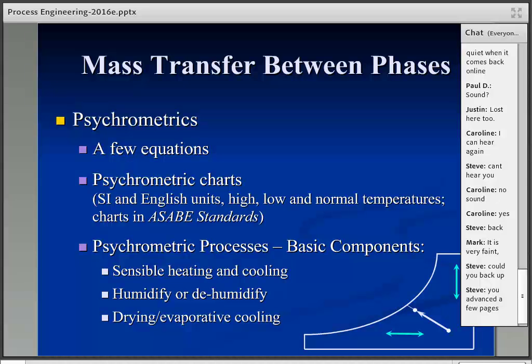If you look at this skeleton psychrometric chart I put down here at the bottom, I've drawn 3 lines on there just to indicate the basic idea on that chart to keep in mind as you're using it. If you've got a process going on that's a horizontal line, moving either left or right, like this arrow down at the bottom, that's sensible heating or cooling, depending on whether it's going left or right. It's a sensible temperature change when it's a horizontal line, because the y-axis of the chart is moisture, basically. So horizontal line means only sensible heating and cooling.